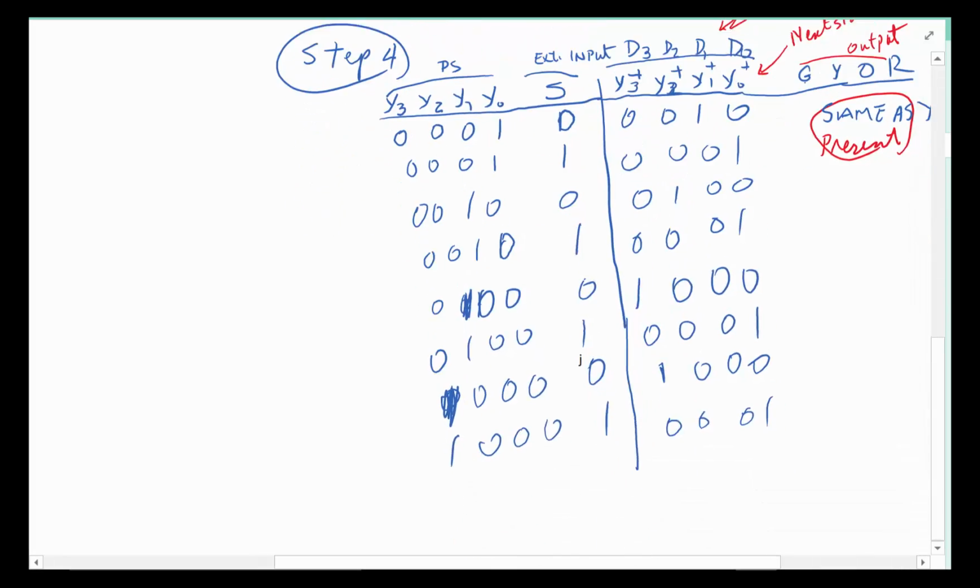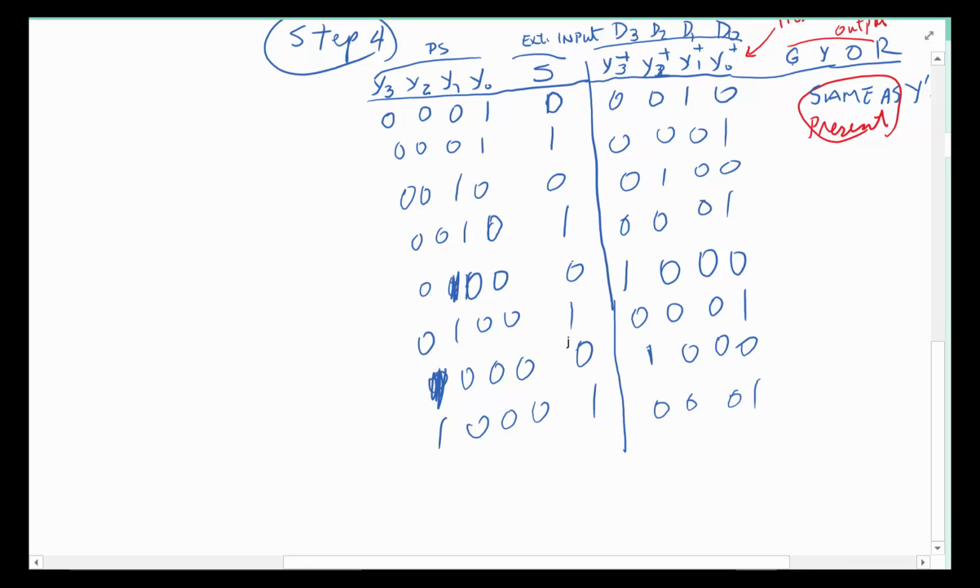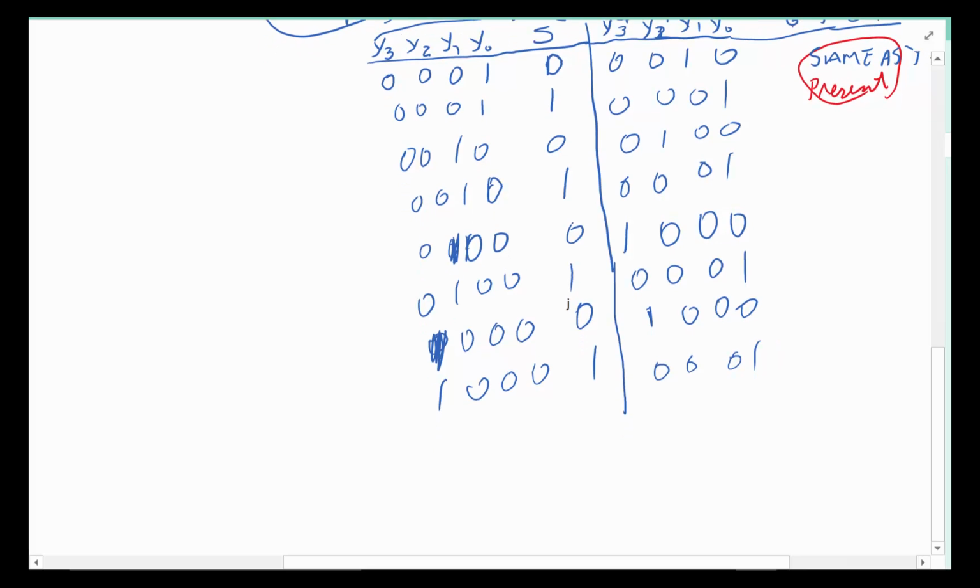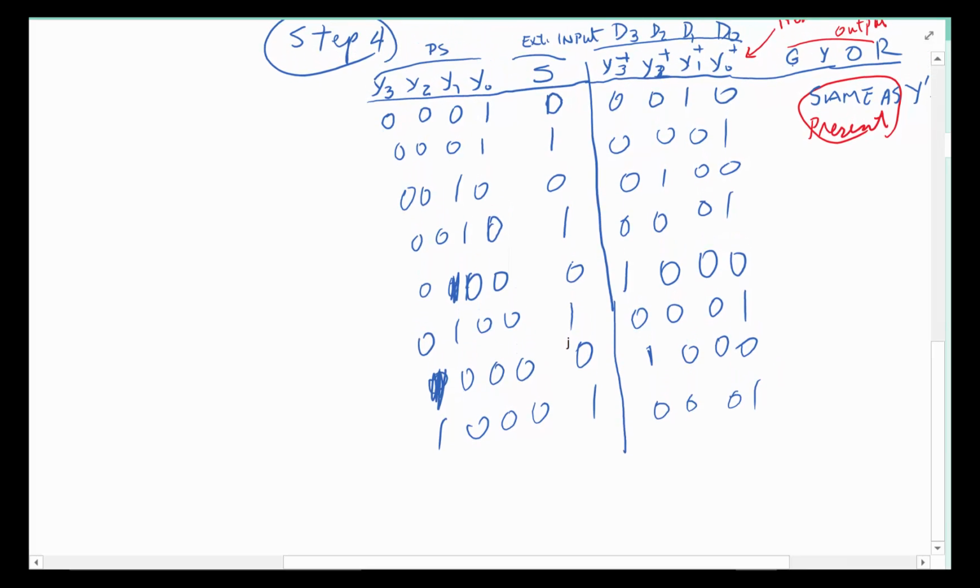This gets kind of interesting in that all the other cases are don't care, and in the case of a one-hot encoding, if you really want to minimize it, you use a Karnaugh map. If you don't really want to minimize it, then we can just go ahead and do it this way, because all the other possibilities are don't care for us. In this case I'll just write it. If there is some obvious minimization, we're going to do it. Otherwise we'll just leave it as it is. So let's go ahead and take a look at that.